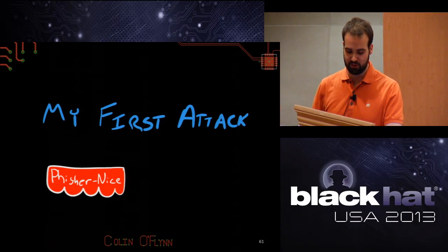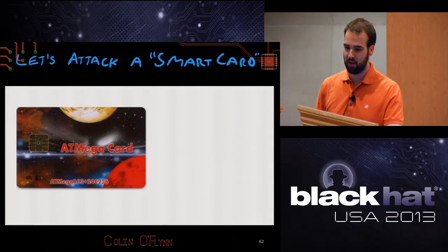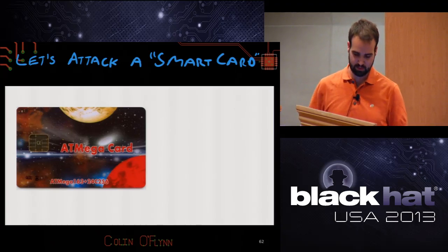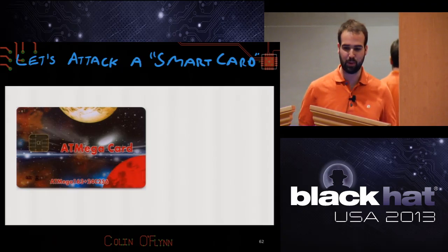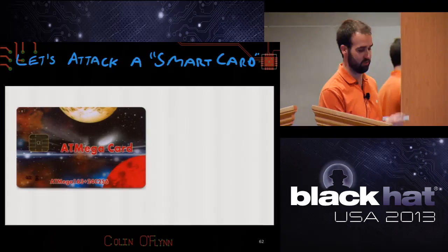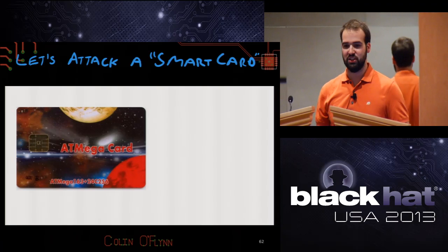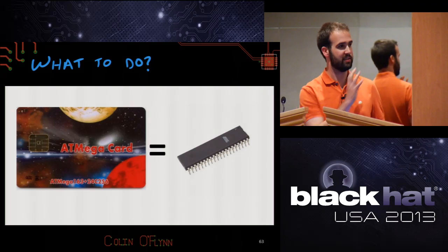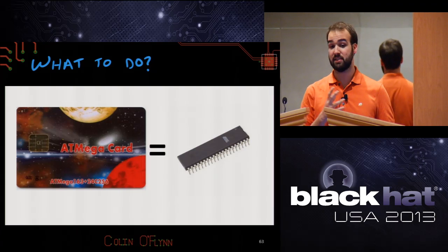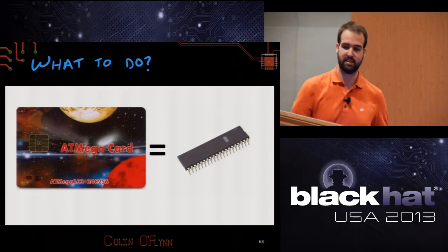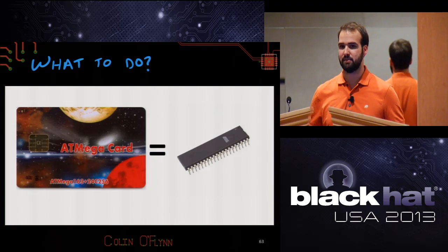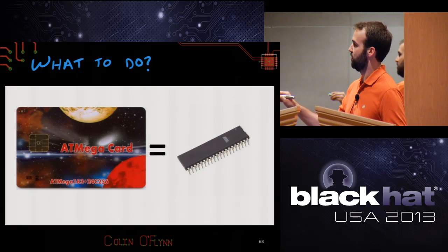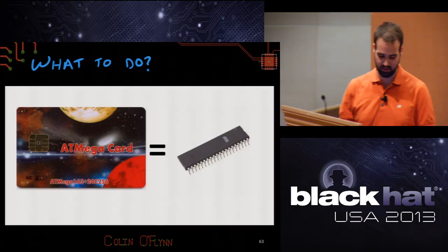So what would your first attack look like? And this is what I'll demonstrate after. You might say, well, I've seen demos with this stuff and they attack a smart card. That's cool. Smart cards are great to attack. The problem is they'll frequently use these cards, these ATmega cards or Fun cards. And these cards are cheats because they are a regular microcontroller that happens to be in a smart card form factor. Nothing about this is special. In fact, you're doing a disservice by using these ATmega cards because they use an old microcontroller that has much larger power signatures because it's a larger geometry. You can buy a recent microcontroller and just program it yourself and you save yourself that hassle.